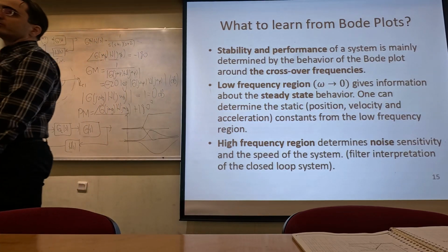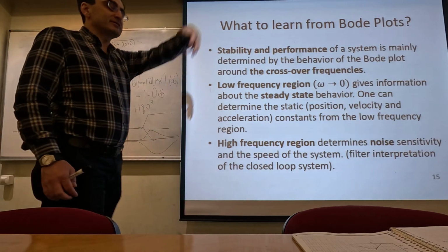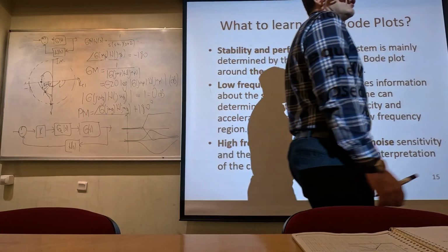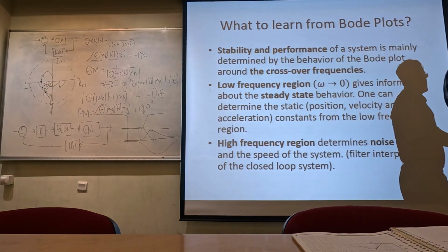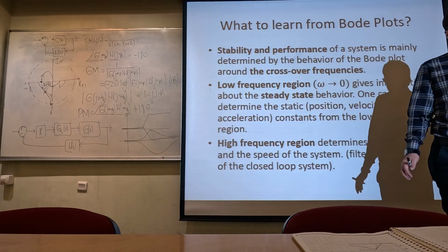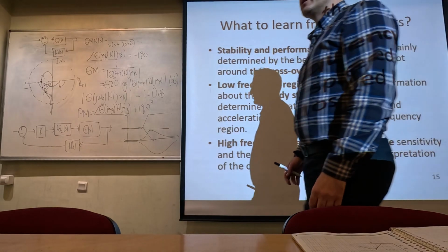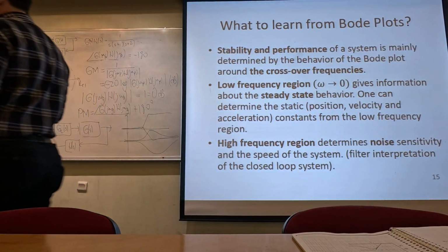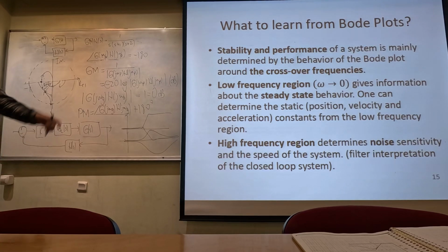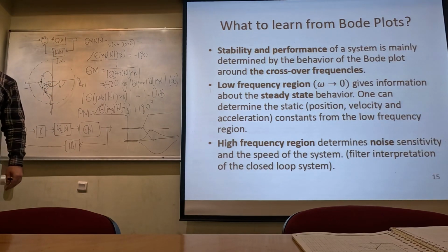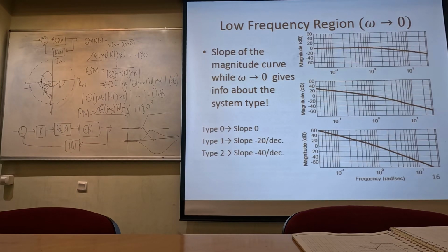the system under noise. If the system has large gains at high frequencies, then this means that the system is going to amplify noises in your system, which is usually not a very good thing, because noise has high frequency. In general, we want the gain of the system to be reduced at high frequencies as much as possible.